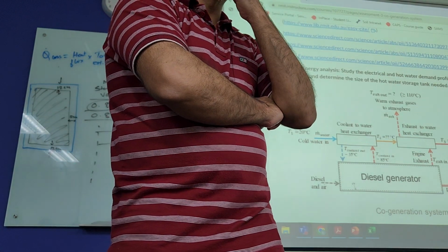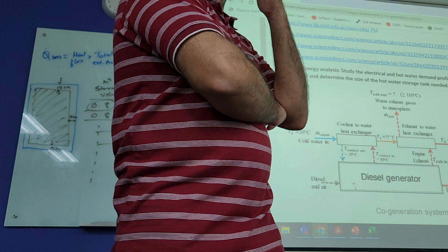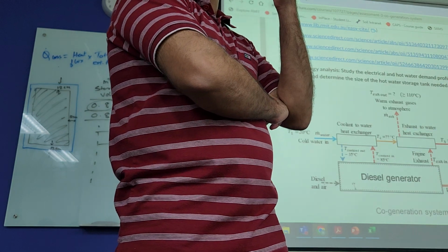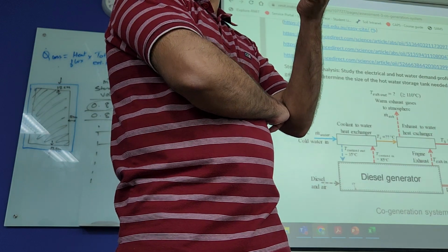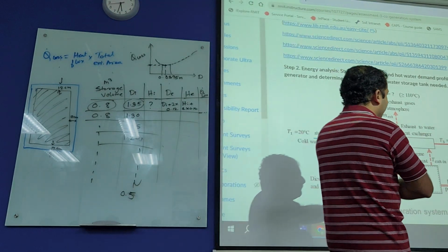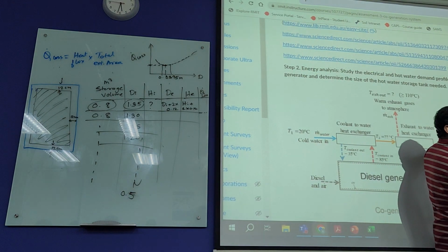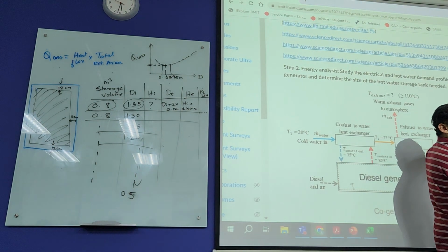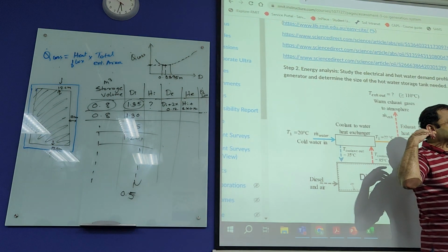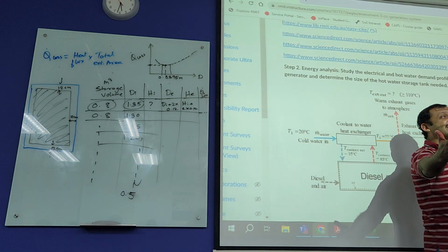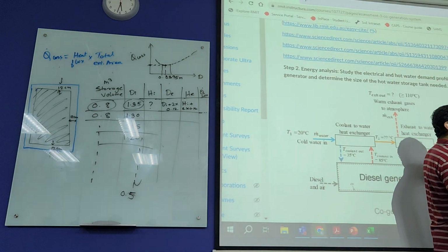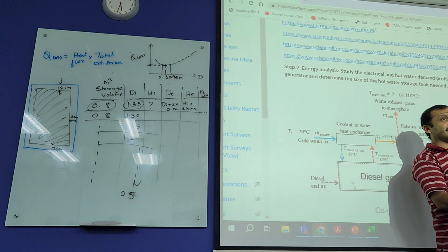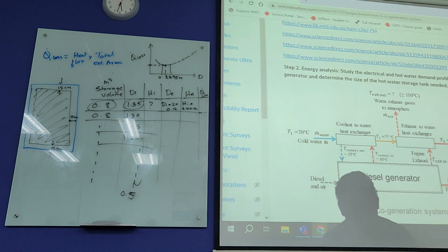Water goes in and comes out, so it should be 80 to 85. Coming out, logically, 80 to 85. Going in, 85. Okay, but if you design it for 80, what's going to happen? If you make a tank which can accommodate water of the mass we calculated, but at the 85 degrees Celsius density, and the temperature goes to 80, anything above 80 is going to expand, and what's going to happen? Practically, what's going to happen? Overflow. Perfect. Good. Start thinking practical.